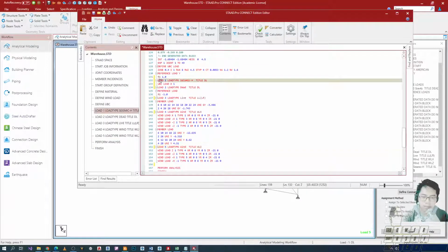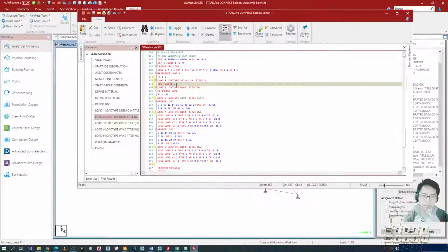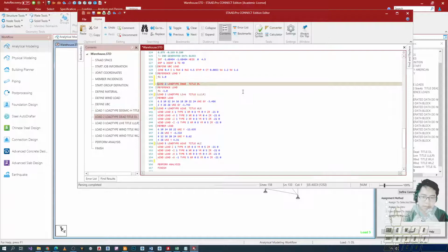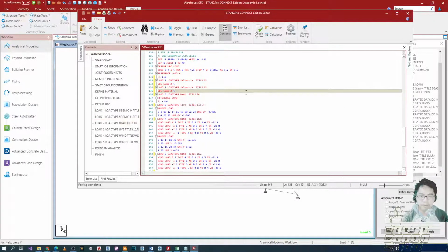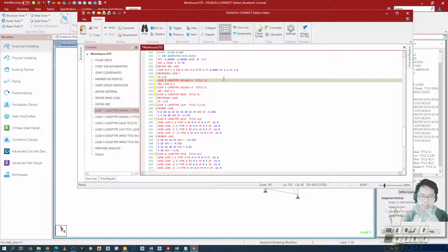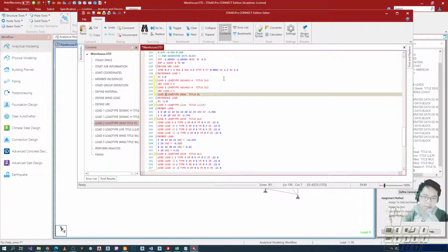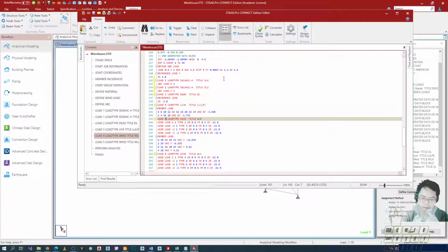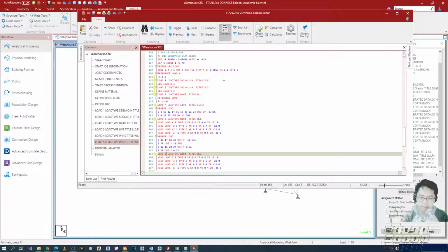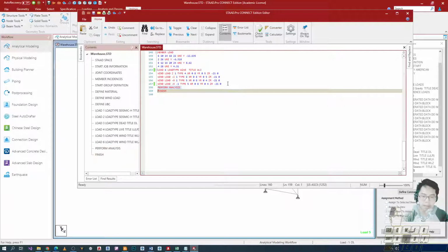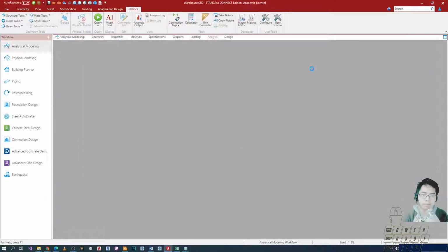Because my load case number 1 is only one Seismic load case, in the direction of X. We should also have Z. Strictly speaking, we should also consider the reversal, so there should be a negative too. But for our example, never mind, let's just use SX and then SZ, this one is Z. Let's fix our load numbers: load case number 3, 4, 5, 6. Okay? Perform analysis will be retained. Let's look at the result, and then we still have some modifications here.